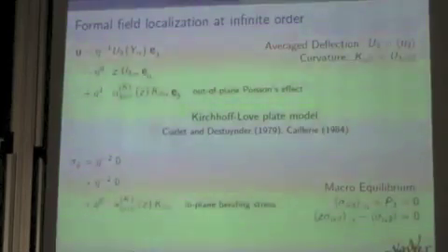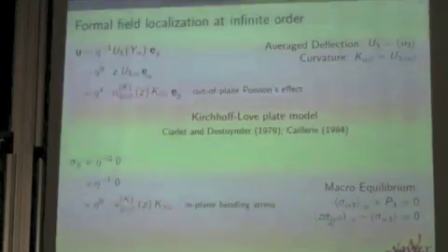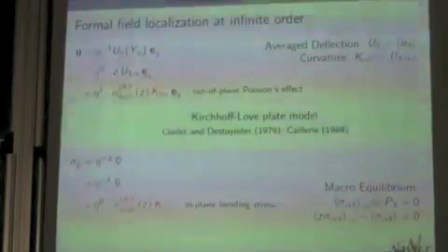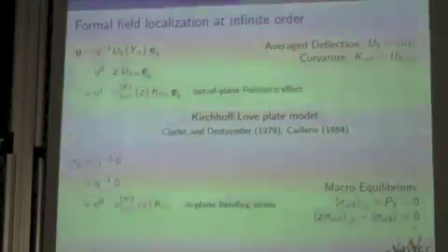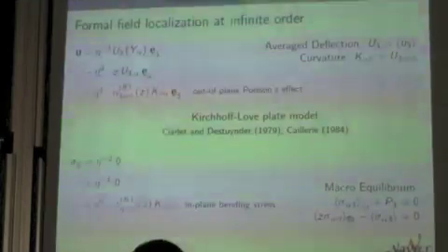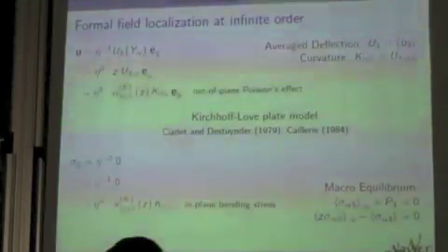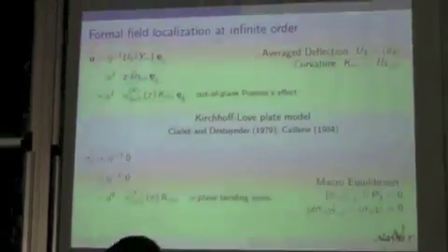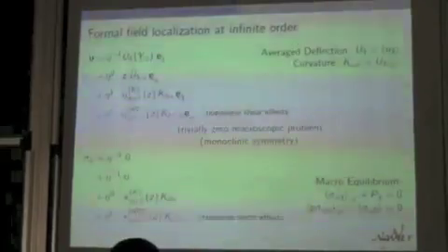The second line is here, you have the bending moment, in-plane stress times z, integrated through the thickness, and you have its divergence, and it's equal to the shear forces. This is why you have a generalized continuum, because you have two resultants with the internal length scale between them. Okay? So this is for the Kirchhoff-Love plate model. As you can see, there is no transverse shear effects in those distributions. So we need to go